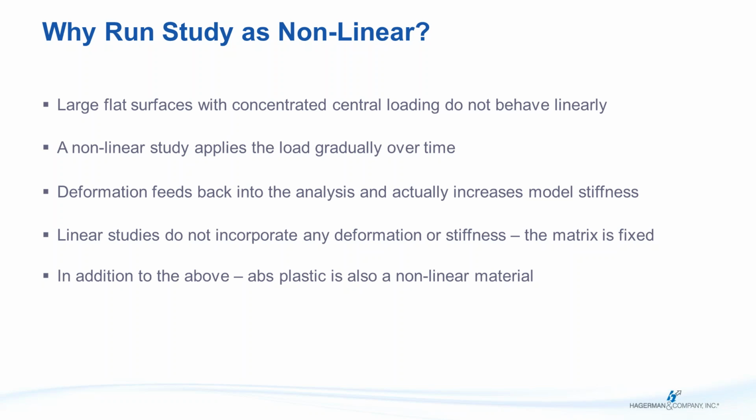The deformation that comes back from a nonlinear study actually can be turned around and fed into the analysis because it can analyze and compensate when material deforms. Sometimes it gets stronger. Case in point, hex head bolts, cap head bolts and screws. Most of those are formed through a cold forge process, and by doing so, they're actually changing the grain structure of the material when they form the head of that bolt. By doing that, it actually increases the strength of the bolt. The same thing can happen with a lot of other materials. Plastic is actually one of them.